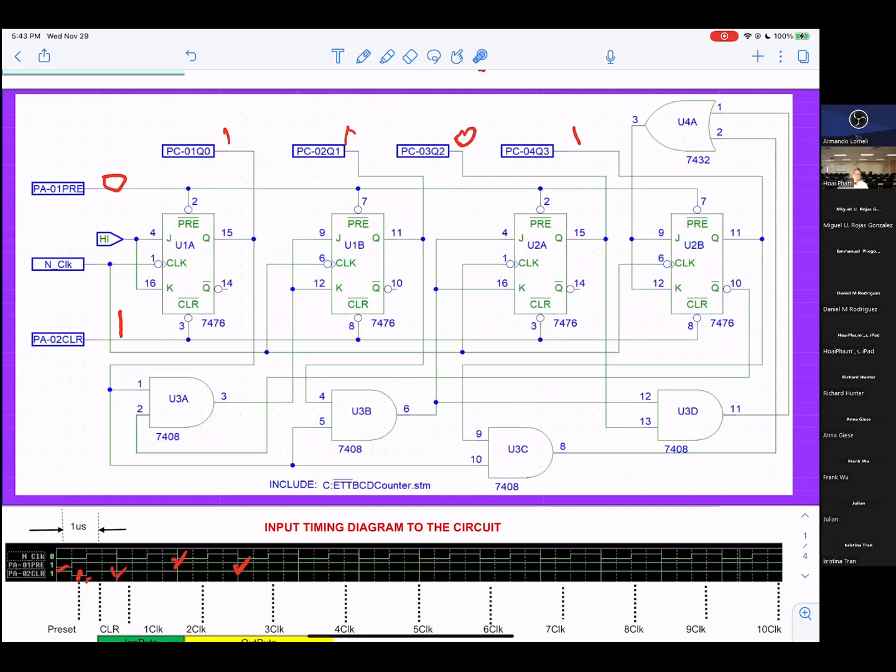Would it be the wiring going from 15 to PC3? Exactly. That is the one I want to talk to you about. Now, if I have to do it, I use the meter to ring out the wire. First thing, you can connect one to U2 pin 50, and go to PC pin 3, make sure they ring out. However, before you ring out the wire, you have to remove 5 volts from your circuitry. Then you can ring out the wire.